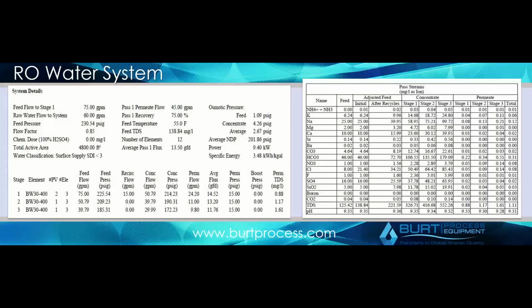One of the things to note, which I get come up a lot, is what's a good temperature for the water to run through an RO system. Most ROs that you see online, for example, that are just advertising generic use ROs, always rate them at 70 degrees Fahrenheit for the incoming water, and that's not actually an ideal range for an RO to operate at. You generally want an RO to operate at a lower temperature.